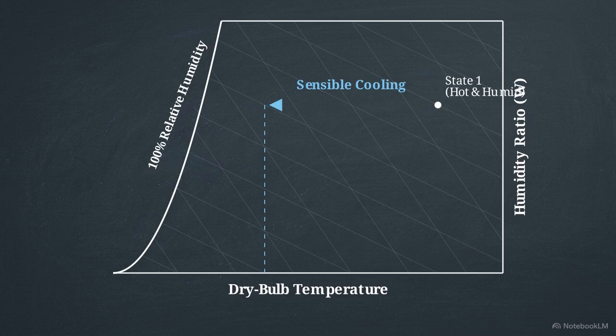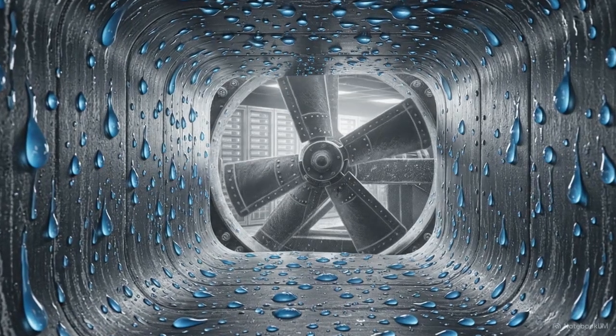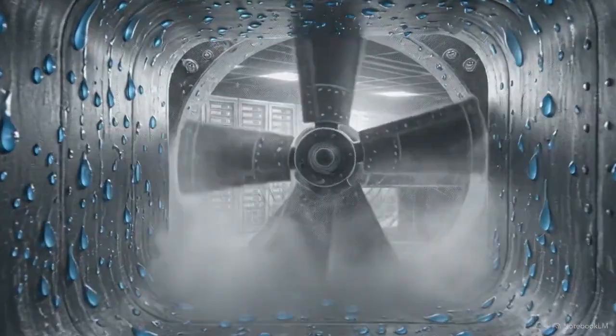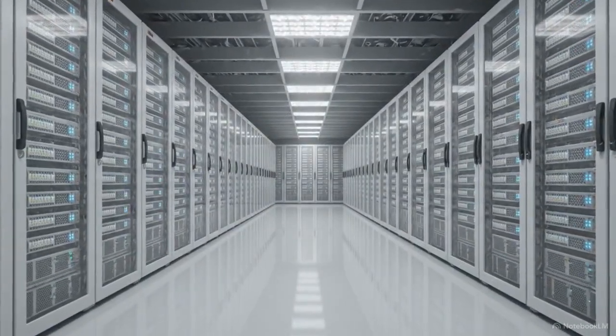Dehumidification removes moisture mass without altering the dry bulb temperature. This plots as a pure vertical drop downwards on the y-axis. Since an actual cooling coil performs both simultaneously, it generates a single diagonal vector, pointing down and left, directly toward the final conditioned state. The psychrometric chart provides a unified visual framework for thermodynamic analysis, condensing the first law, Dalton's mixture laws, and complex phase changes into actionable geometry.